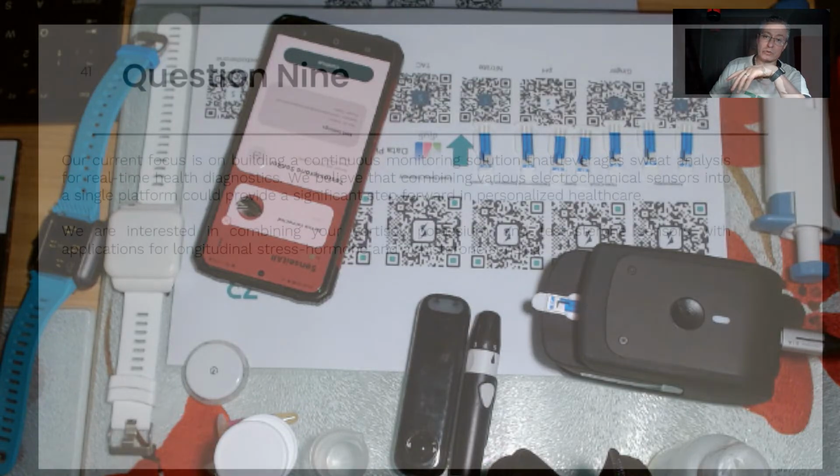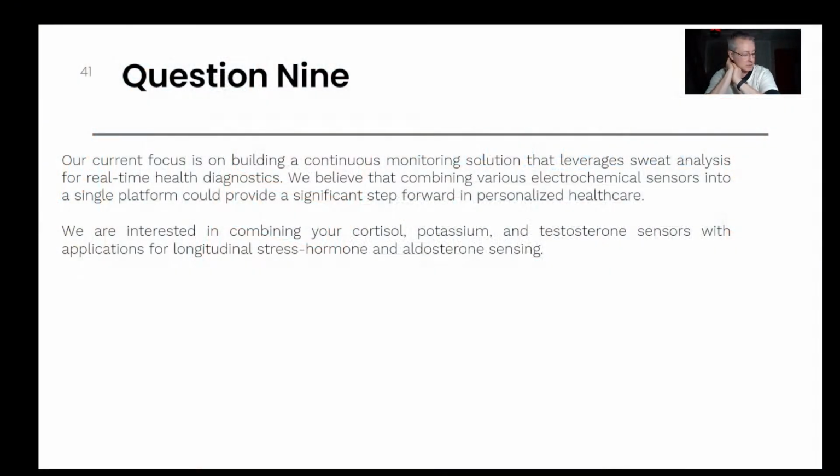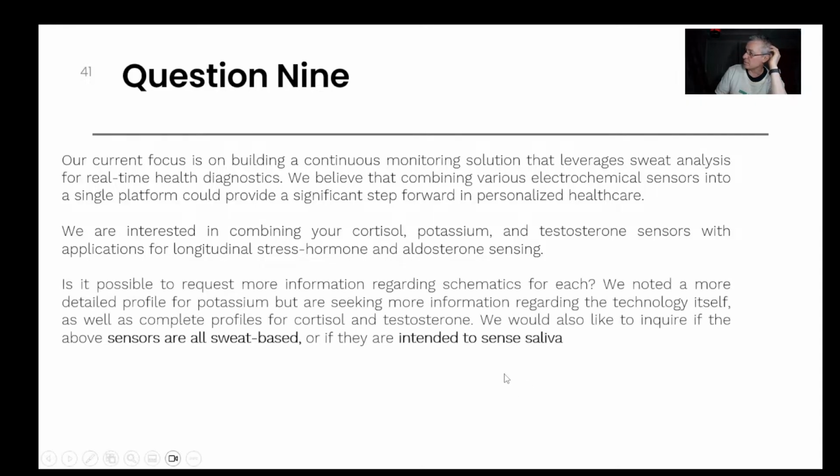But when groups are university based and have a very limited budget and very limited time, I have to strongly make my recommendation. My recommendation is focusing on potassium. These electrodes from ZP, biosensors, don't really care what the matrix is. They don't care if it's blood, urine, sweat, saliva, tear fluid. It is important because it affects the calibration routine or even the analysis routine, but the sensors themselves don't care.